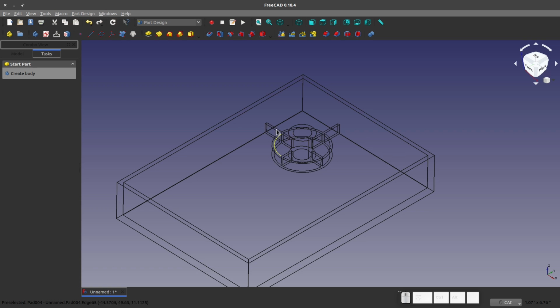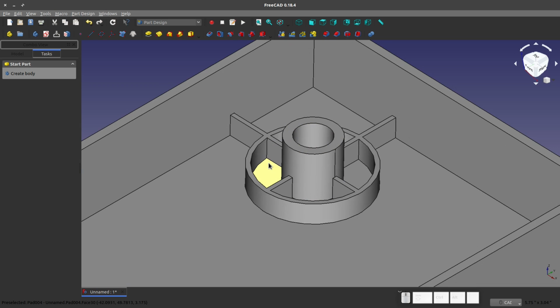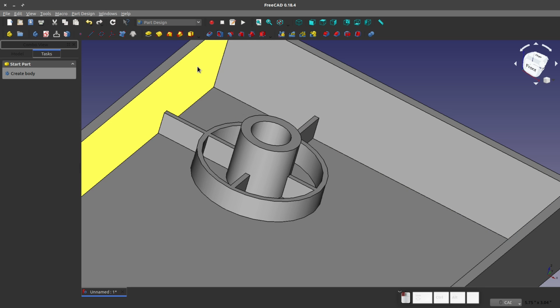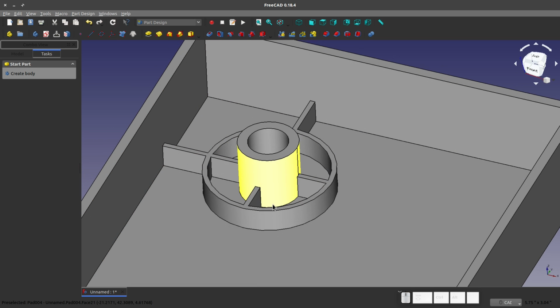So there we have a set of support ribs on this boss. And people break these injection mold rules all the time, right? They can make ribs taller or wider or whatever, and it can work, but these are just the guidelines for being ideal. So I've got this little rib system. And how far apart should my ribs be if I've got parallel ribs? They should be 3 times your wall thickness at a minimum. Any tighter than that, and you're going to get more sinks, more voids, and ejection issues, probably. So keep that in mind.